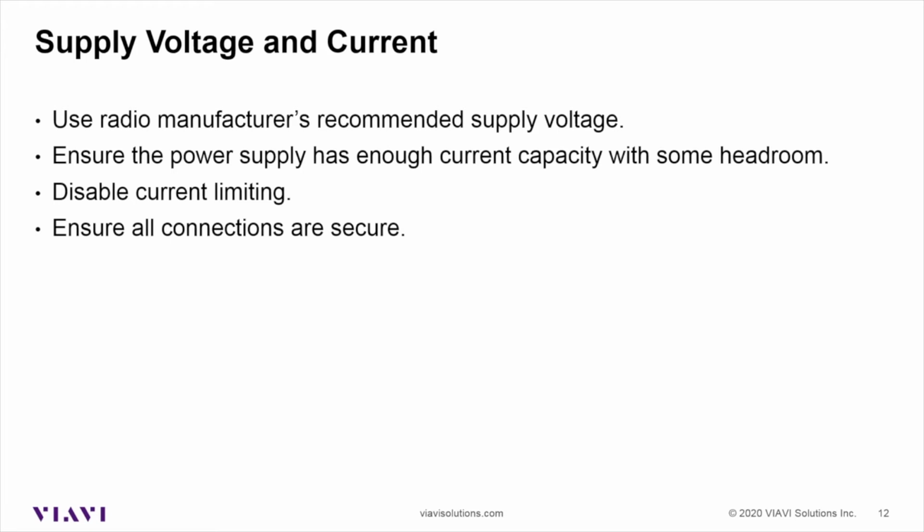So I've had customers who have used power supplies with banana jacks, and that's great, it's convenient. But the banana jacks a lot of times don't have a very big opening for wire. So in this case, they had 8 or 10 gauge wire, but they couldn't fit very many strands of that wire into the banana jacks, so they just trimmed back a bunch of those strands, and they ended up with like 3 strands of wire going into the banana jack.